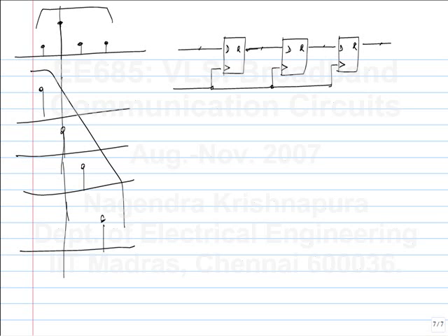So what do you assume for the input data in this case, if this has to work? If all the signals have to be separated by 1 cycle of the clock? No, the input itself has to come from a rising edge triggered flip-flop, right? That's what I mean. For instance, if the input changes arbitrarily, these three will still be spaced by one cycle, but the spacing between this and this will not be one cycle of the clock.